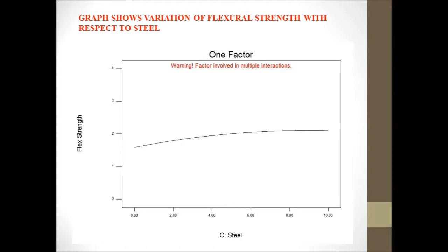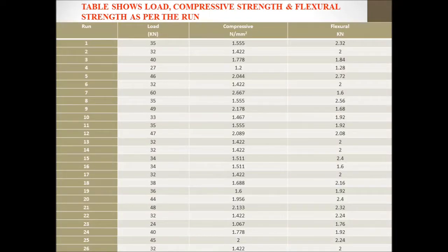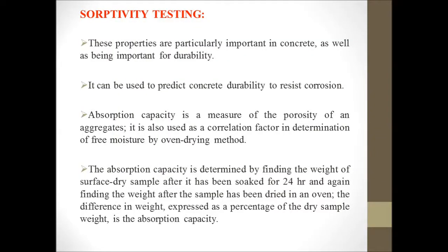Next is sorptivity testing. This table shows the load, compressive strength and flexural strength. Sorptivity testing is absorption testing. The cube is painted all over the surface except the top and bottom, and then it is kept in the sand